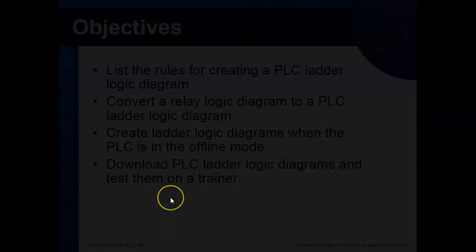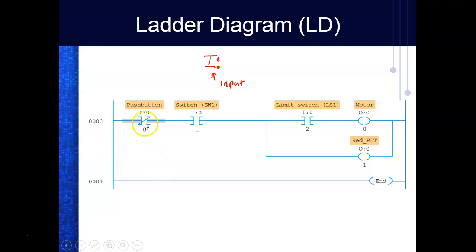So what I would do is I would come over here. So this is input 1, 0, which says it's a normally closed, but we're going to talk about this, guys. So I would address this. The way we enter the address is I would put input colon, and it's going to be slot number 0, even though it's not technically a slot. And then what we do is we put a slash, and then we put the port that it's connected to.